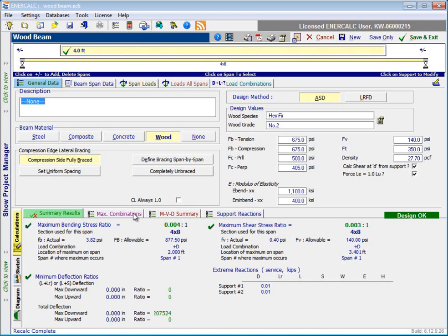Continuing down the screen, the third area that we have is what I refer to as the results panel or pane. This is the location where you're going to get information back out of the program after you've performed the analysis and design. And you can see that it's organized with a series of tabs on the vertical axis here, and then each of those has some options associated with it. And so that's where we'll complete our video today, is by walking through all of the various options that are provided for you to extract information regarding the analysis and design results.